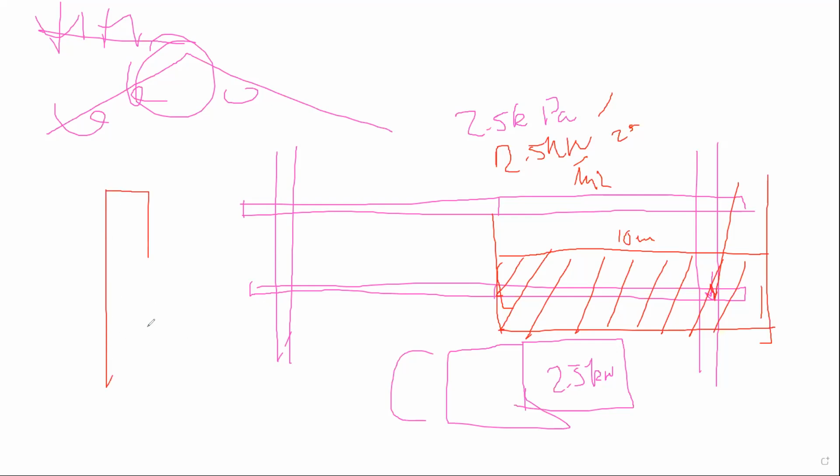And that's what you have to actually design for. In other words, what is the actual force going through the stud, so that you can make sure that the stud, depending on the sheeting and all that, can withstand that force without breaking. And then of course the exterior stud: you don't only have to worry about that force, you also have this wind load acting on it, okay?